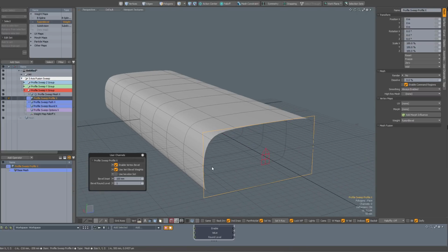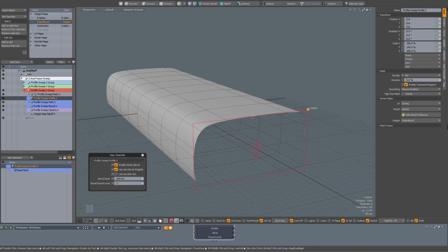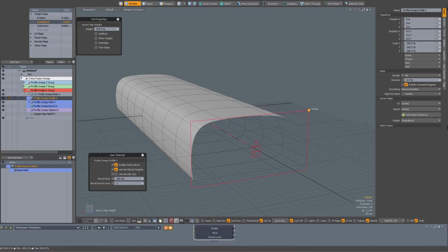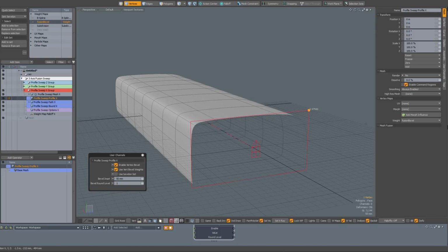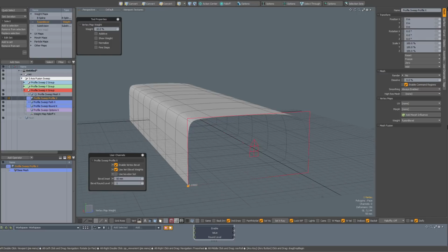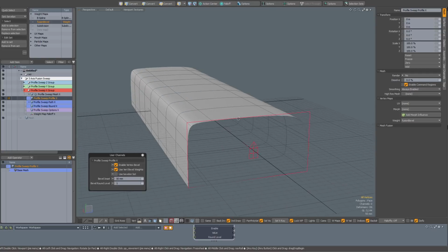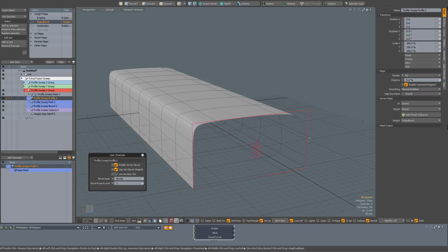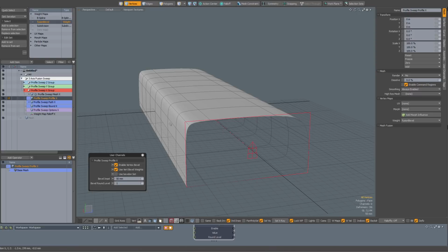So right now the vertex bevel is going to be performed on every vertex, and with the vertex map weight tool I can adjust the weight and maybe set my bevel inset back to 50% of 50 millimeters. So again, Shift W, and you can also, while the tool is active, enter a value straight on, drop the tool, Shift W, just like that. So that is the advantage now in Modo 12, since you have that weight map falloff. I am working with a simple polygon with 4 vertices, but I get an extrusion which is completely being customized.